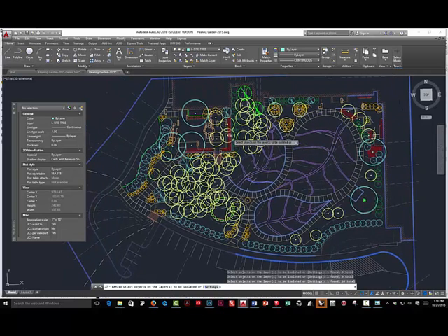So clearly, how you organize your layers in an AutoCAD file, if you do it very well and very logically, then you can pull out those pieces that you want. If you have these lines and these lines on the same layer, then it gets to be a problem. That's why we've taught you, Professor Goldberg went over how to set up those layers and keep those bits of information separate.